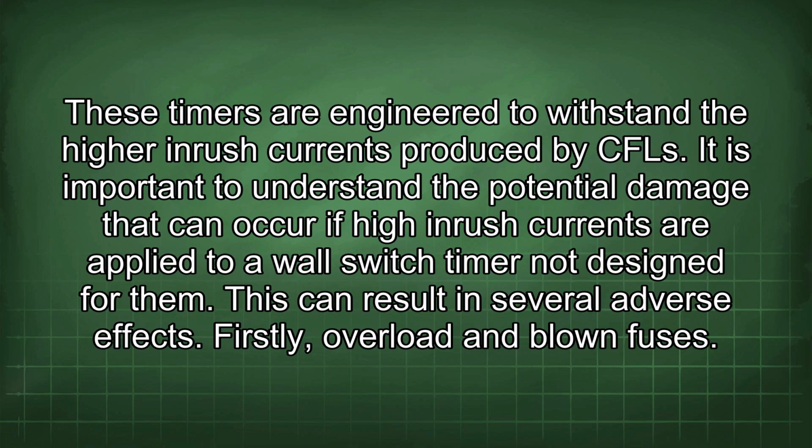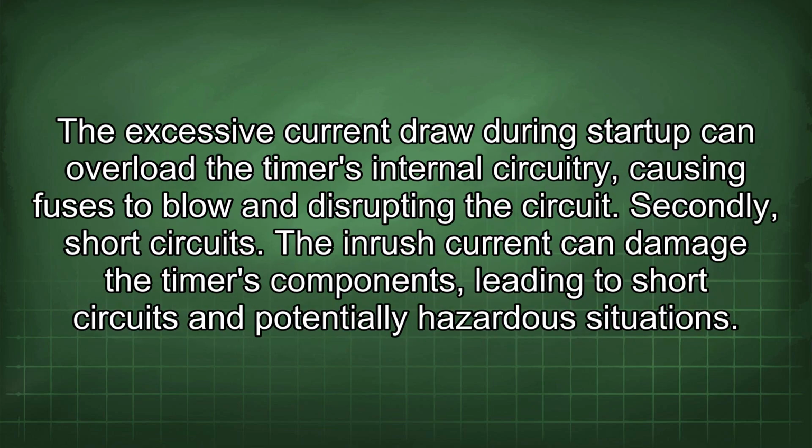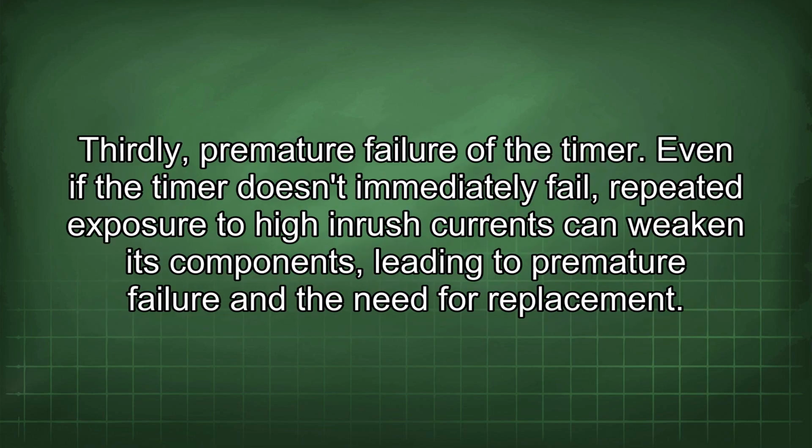Firstly, overload and blown fuses. The excessive current draw during startup can overload the timer's internal circuitry, causing fuses to blow and disrupting the circuit. Secondly, short circuits. The inrush current can damage the timer's components, leading to short circuits and potentially hazardous situations. Thirdly, premature failure of the timer. Even if the timer doesn't immediately fail, repeated exposure to high inrush currents can weaken its components, leading to premature failure and the need for replacement.